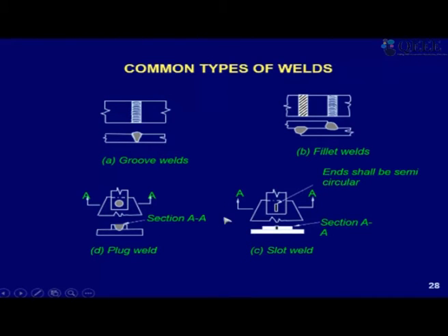So basically these are designed as fillet welds, and this is the butt weld. Okay. And for a butt weld, we actually don't need to do any design. We just need to take care that the weld metal is stronger than the parent metal, and that we have done the full depth weld, the full length, full width of the plate is welded, so that when I pull, the weld will be stronger than the parent metal, and the parent metal is the one which will yield first.